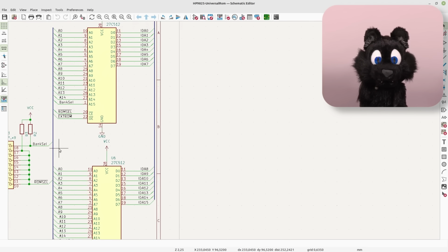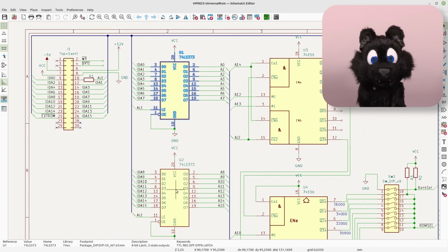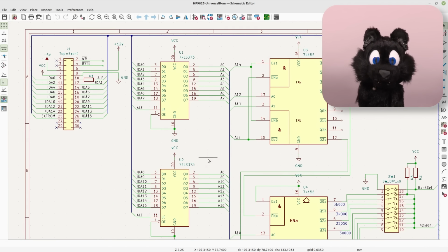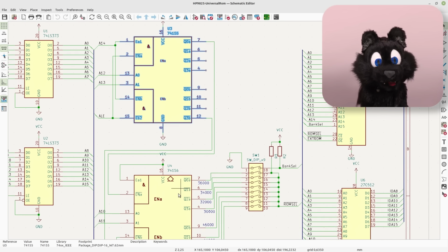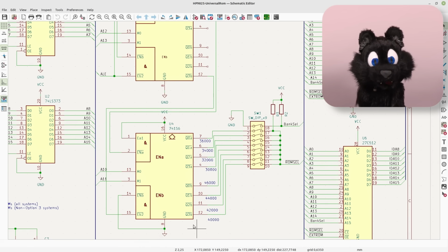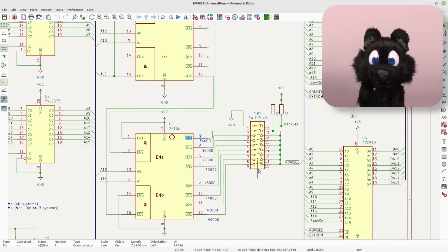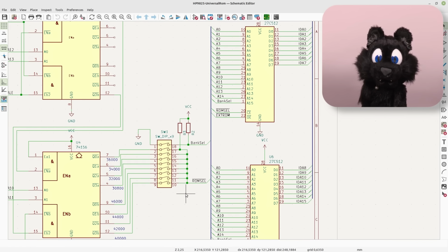Plenty of space. What we need is, like with the RAM, an address latch. Check. Next, we need an address decoder circuit. Since we know what range the ROMs can be, we can decode any of these addresses and provide dip switches to select which block to enable or disable.